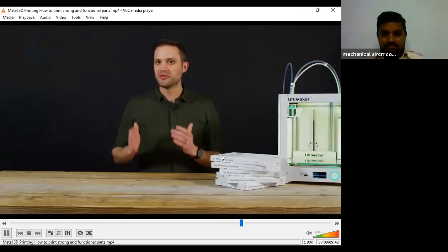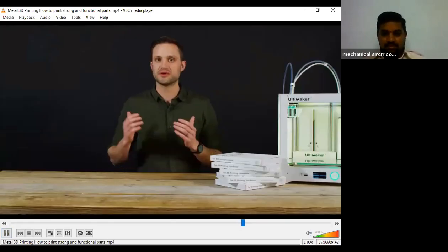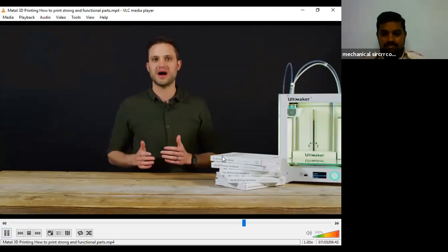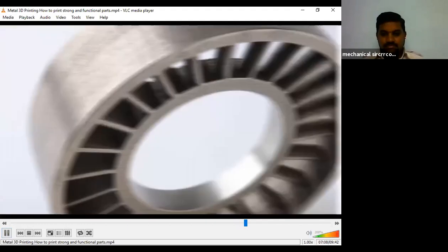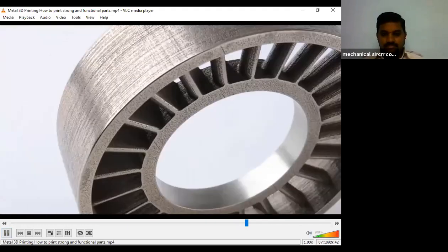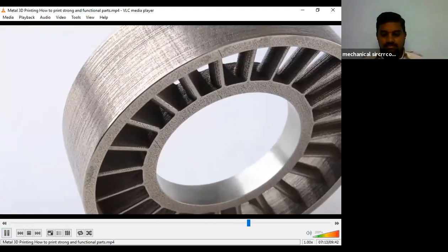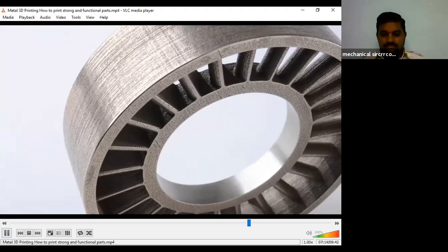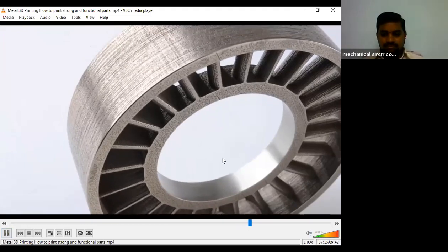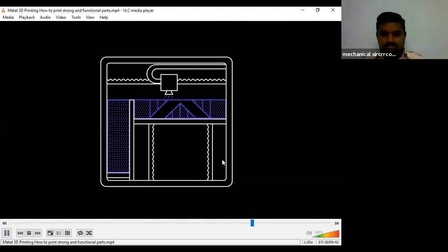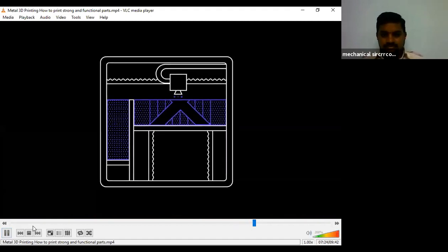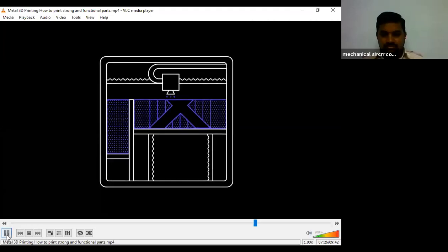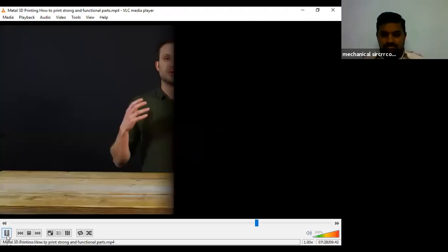As I mentioned earlier, there are several other printing technologies that are becoming popular alternatives for producing metal parts that are not DMLS or SLM. Metal binder jetting is one such example. Its unique way of producing parts makes it perfect for low to mid-volume production runs. Binder jetting builds parts by depositing a binding agent onto a thin layer of powder through inkjet nozzles and slowly builds the part up one layer at a time.